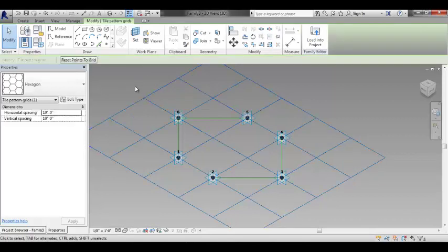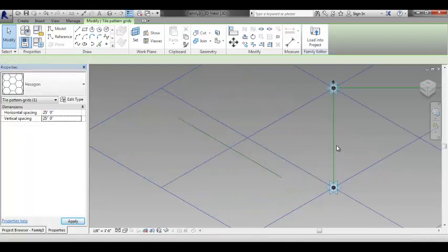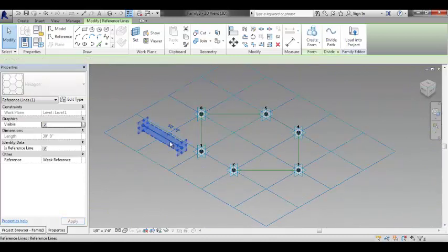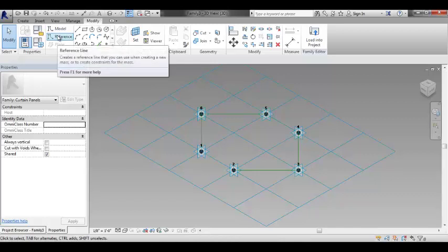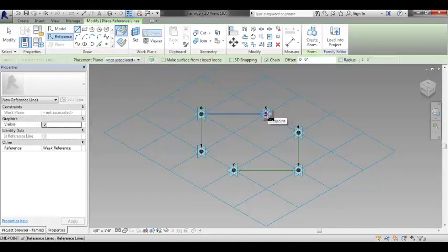And how I flex and check this is I take my spacing on my grid and I'm continuously toggling new spacings on my grid to kind of flex that. And you'll see that it didn't stick at all, right? So great, here we go. All right, so now I got to try and figure out a different way to do it. So in this case, I'm going to do it as the reference line going from point 5. So I'm tabbing through to make sure that I'm specifically on the point. So you'll see the difference between being on a line versus being at an intersection versus being at nothing versus being on a specific point itself.